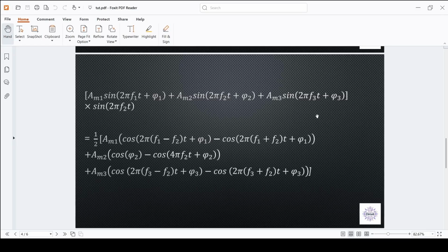This is very useful because even if F1 is, let's say, only 100 kilohertz apart from F2, if the accuracy of F2 is within 1 kilohertz or lower, we can effectively look only at F2 and remove all other tones with this technique.